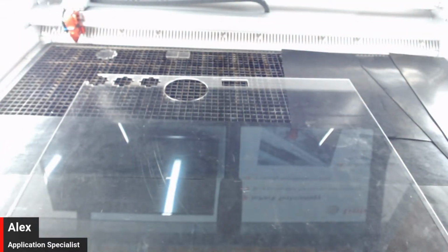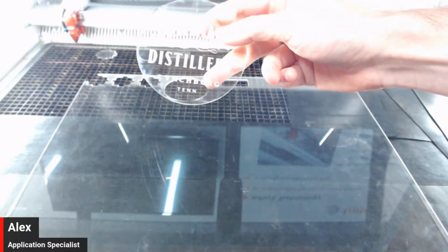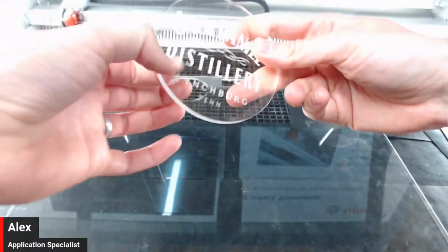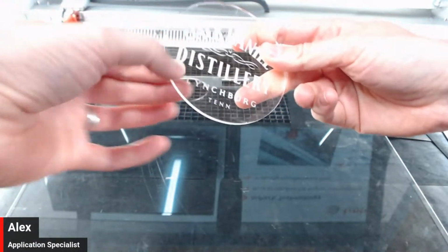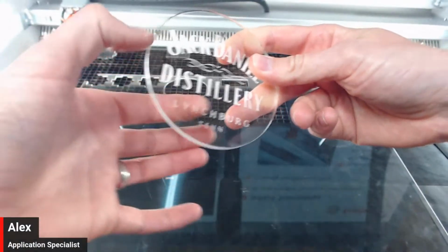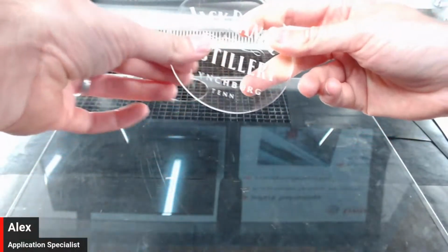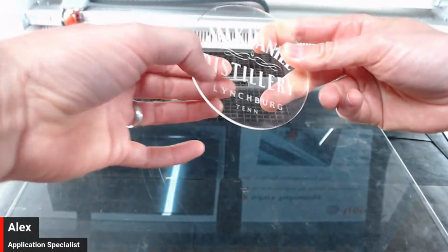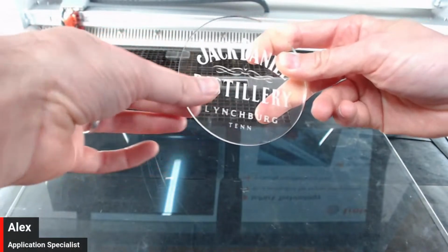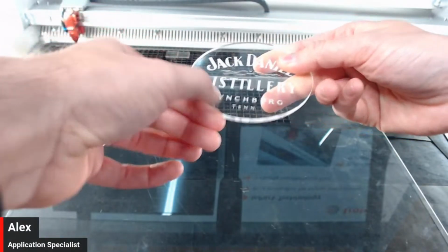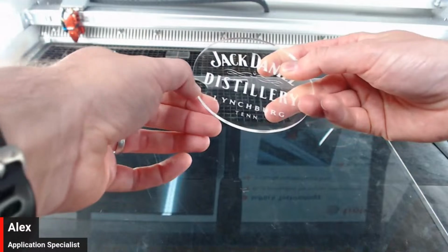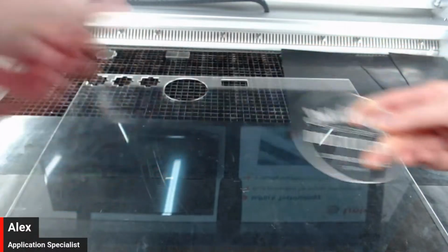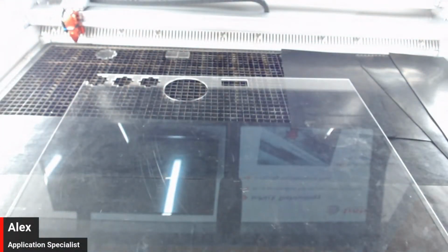It's always hard to see these things on camera, but we have our engraved acrylic here, and there's really no depth to this engrave at all. So we've got this contrast, but there's really no depth at all. That also stops any of that extra material that could deposit into the surface that can be quite hard to clean off as well. So we're just engraving enough to get this contrast and this very slight depth that an LED would then start to pick up.